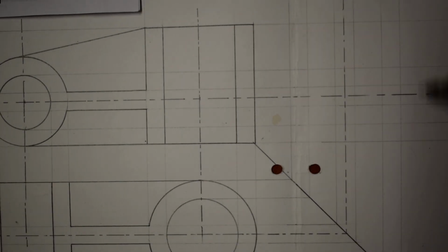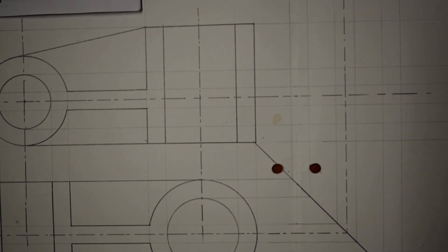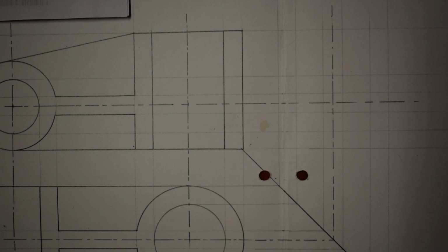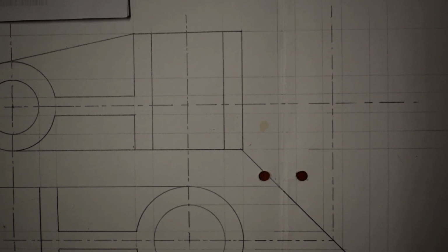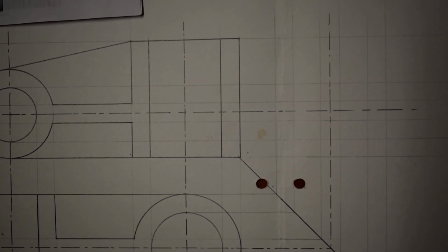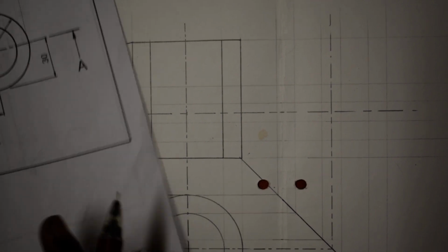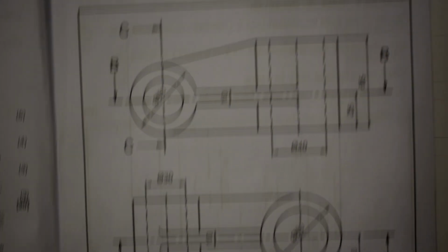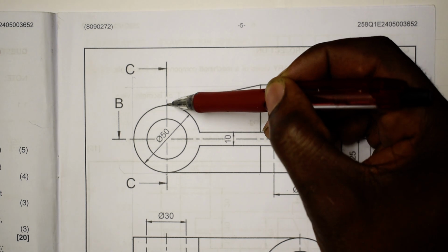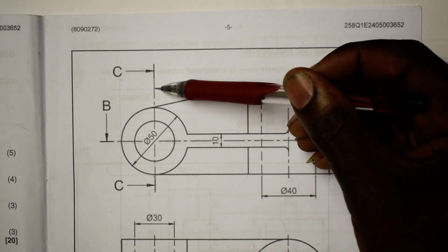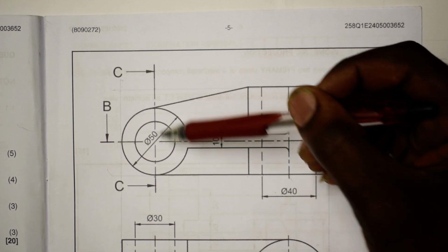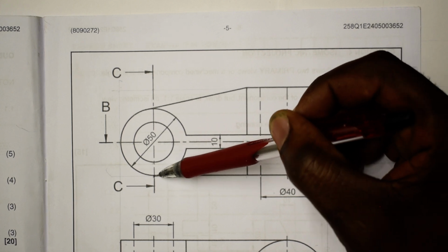So which means here I have to be able to get my left view. What I've drawn so far is a constructional line, and they must be constructed. Okay, so now what is going to be pointed by the one that is going to be in sectioning? Remember, now we are dealing with CC. From here till here the hacksaw didn't cut anything. From here till here the hacksaw didn't cut anything. From here till here it cut it. Then from here till here it didn't. From here till here it cut it.